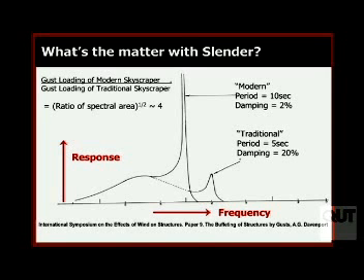If I have a lower frequency, a longer period, I would have a much higher response at that frequency because of the nature of wind loading. And so as we move from more traditional, heavier construction of higher natural frequencies down to lower natural frequencies, we'll get much bigger response. And so this idea of looking at slender, tall buildings is going to be a problem for engineers in terms of the response of the structure under loading.